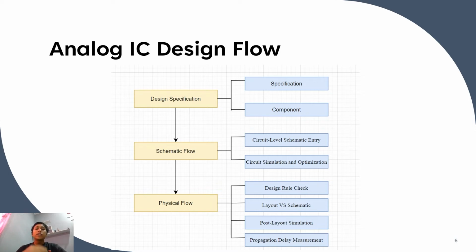For design rule check, we verify whether a specific design meets the constraints imposed by the process technology. For layout versus schematic, we compare the extracted netlist from the layout to the original schematic. For post layout simulation, we extract physical information from the layout. And for propagation delay measurement, we calculate the propagation delay of the circuit.